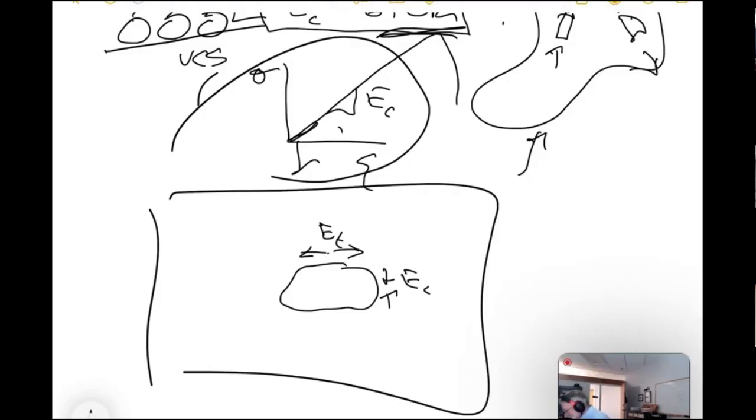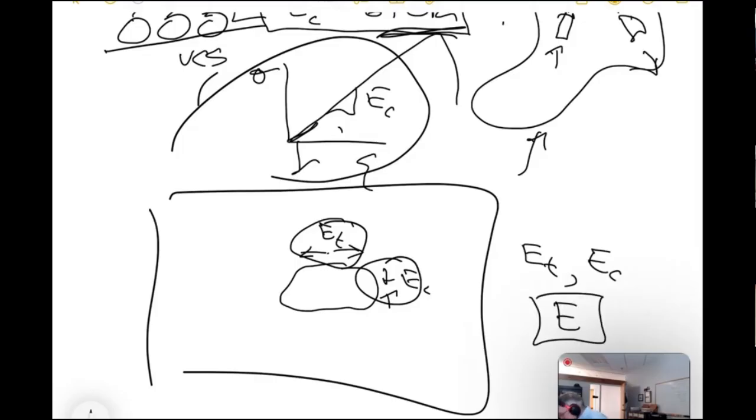This is almost never accounted for in any kind of rock conceptualizations. This could be done. You could even build a continuum model. Well, it's not obvious what you would do, because you would have to build this in, because you don't know where the tension's going to be and where the compression is going to be. That's based on the loading configuration. So very few constitutive models give you two input parameters. In principle, they should. They should give you two E's, but typically they don't. They just say, give me an E. And then they assume it's linear elastic isotropic behavior.